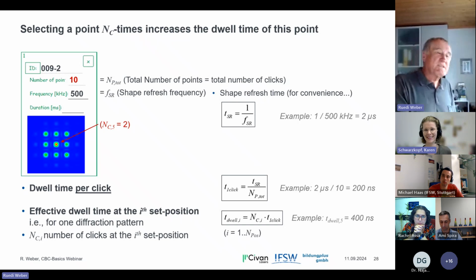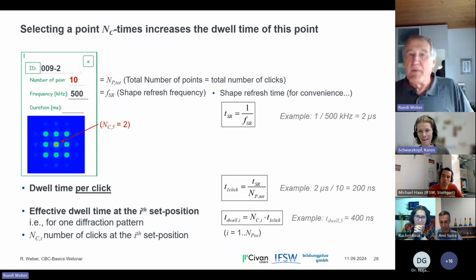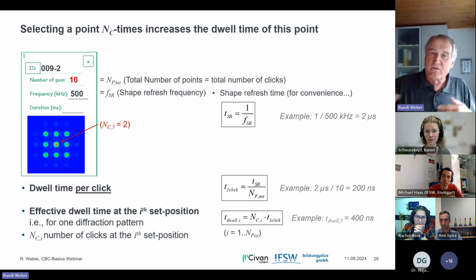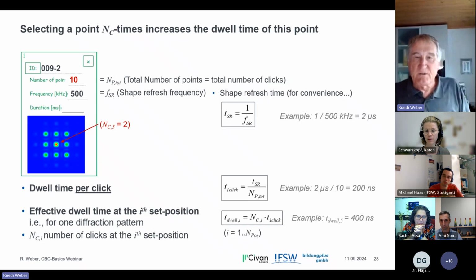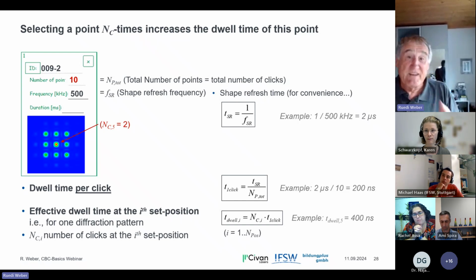Okay, thank you. Probably stays on the last state, but maybe if you have discharge or, I don't know what, reflection in the cables or whatever, it might do something in between which is not really controlled. And if you are close here with your click time to the minimum click duration of 12 nanoseconds, then I guess this might cause problems. That's a very, very good question. Thank you.